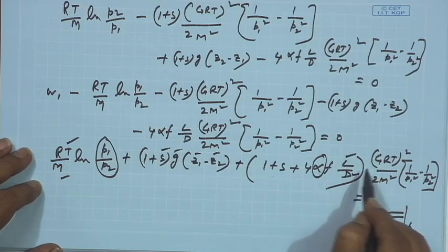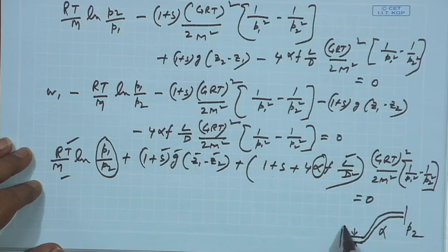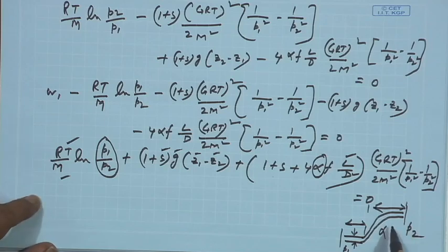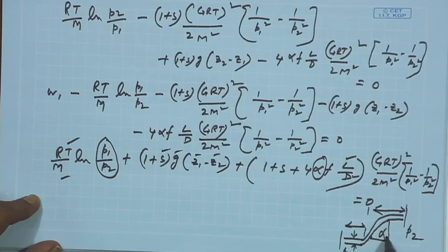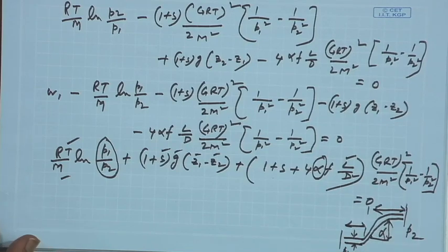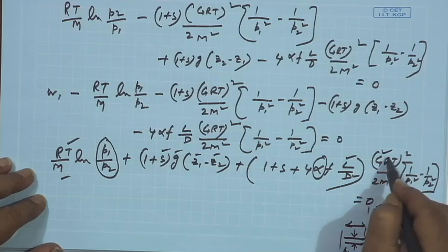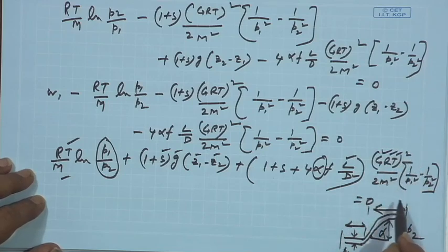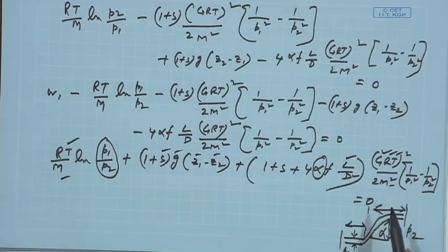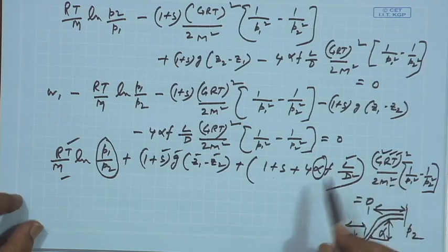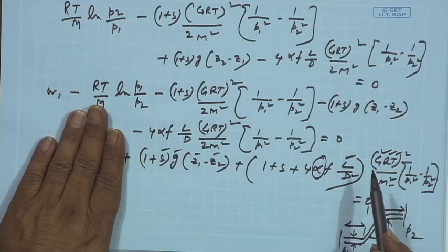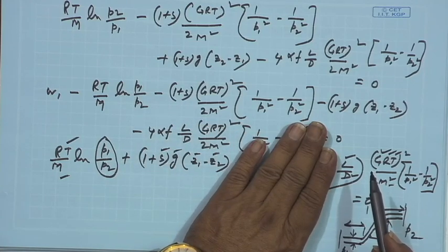For that, the diameter, and the length, how much length it has covered, if that is known, and how much Z if there be at all, how much that is conveyed. If these parameters are known, your G mass velocity is known, R is known, temperature is known, and M, that is the molecular weight of the conveying medium, generally it is air. If that is known, then you can play with that. Okay, I know the pressure at the inlet and outlet, let me find out the coefficient alpha.